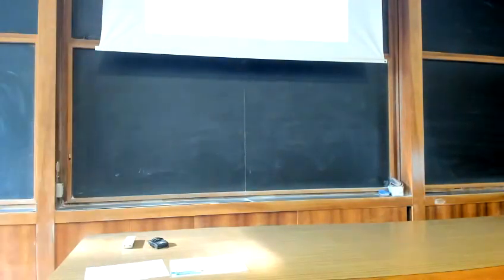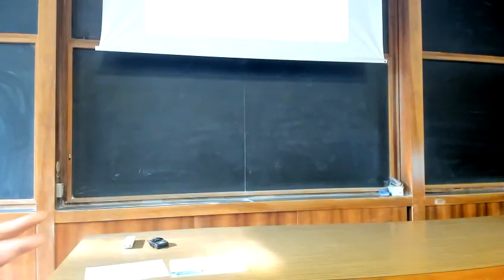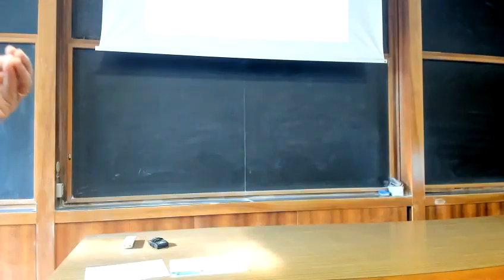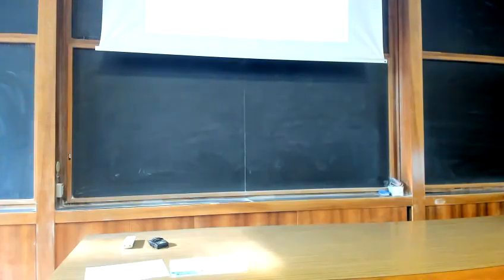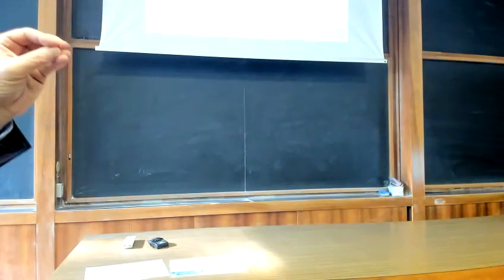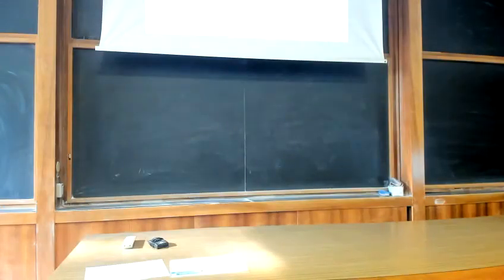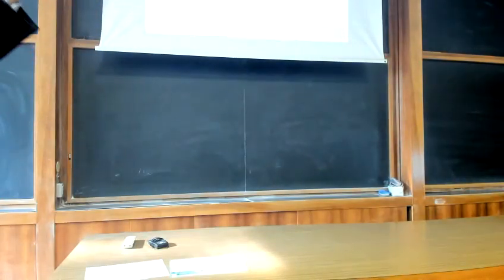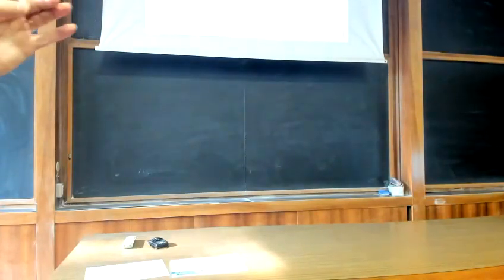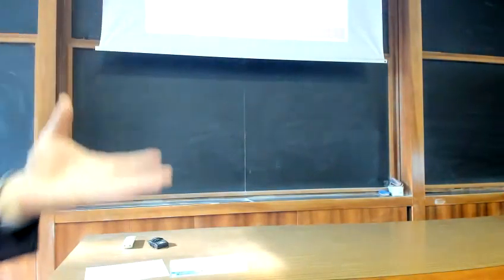It is valid, once again, only under the assumptions we have recalled in the first part, but then the crucial thing is the parameters, especially the soil parameters, that you insert in that formula, because you can easily get to a value which is twice as much as the other, just because you have a phi value which is different by 1 degree or 2 degrees.